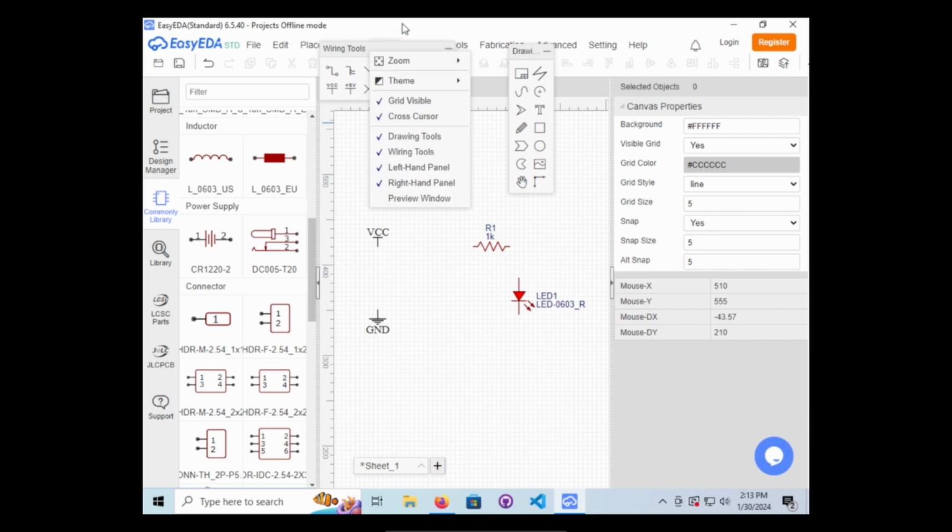You also can, if you send your board to be produced and actually to an assembly line where they assemble it, you'll actually send them that bill of materials and they will purchase the materials and actually assemble the board for you, which is always nice. So you always want to make sure you get it right. Sometimes those change because they won't be able to get those items in stock, and you'll have to actually do more research into that. Interesting.